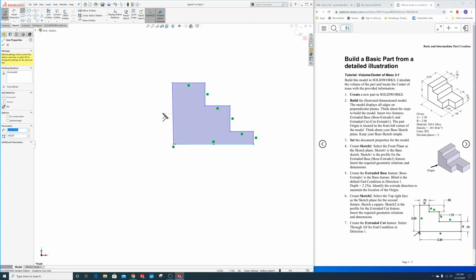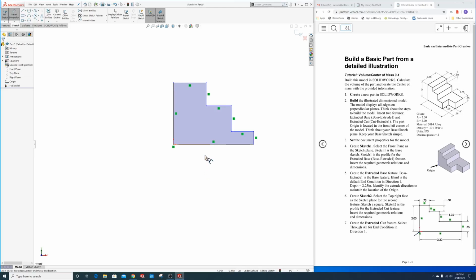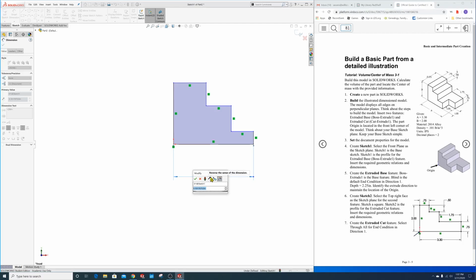And what I'll do is I'm just going to click on that and now make it vertical. That's how I correct my mistake. All right, so if we start looking at our dimensions, I'm just going to right click and drag to get it to my dimension, and I'll go right here and come down, and that is supposed to be our first variable A. So I'm going to go equal, so I'm hitting equal on the key, go to global variables and hit A, and so there's my first dimension.